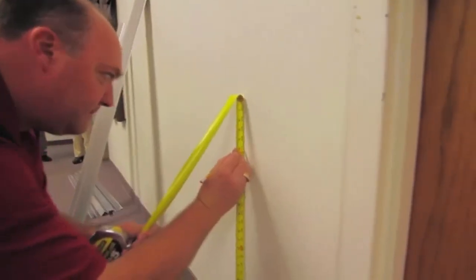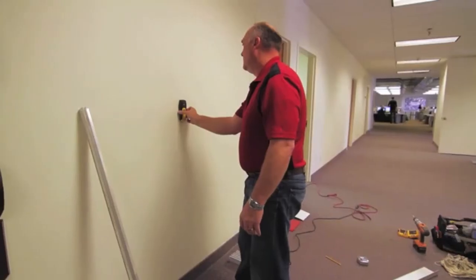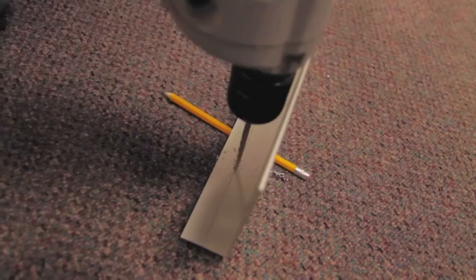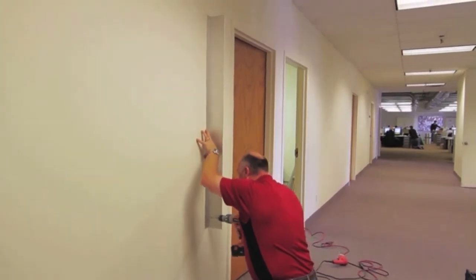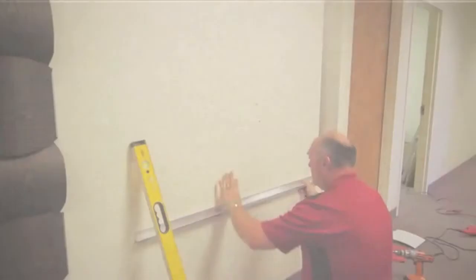Before you begin, measure your space appropriately and find structural studs for installation. Mark and drill the holes in your extrusions to match your measurements. Place the first end of the edging extrusion in the desired position and attach it to the wall with screws. Fit the bottom inner extrusion at the correct height, flush with the end of your edging extrusion.